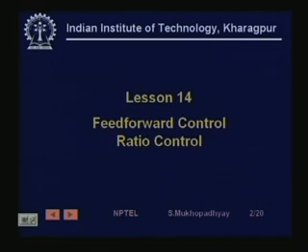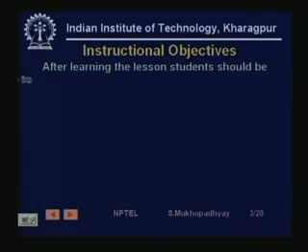Today we are going to look at feed forward control and ratio control. So far we have always looked at the classical control structure, but today we will look at some other control structures which are fundamentally different in principle.